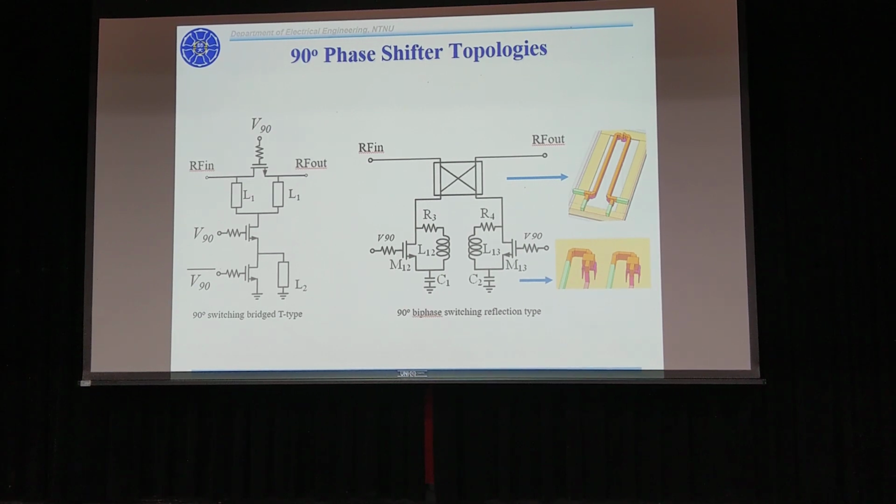To keep the balance of the loads between the reference state and the phase shift state, we shunt a resistor to increase the loss at the control voltage. Because it needs a transmission line to connect the capacitor and resistor in the actual layout, we add the transmission line to the simulation in order to make it more accurate.